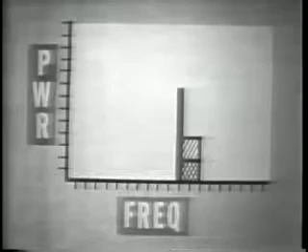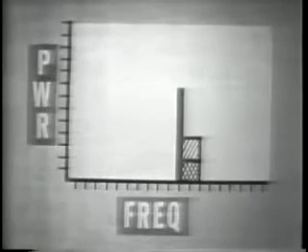And we'd still have the same intelligence in the remaining sideband. And by putting the power from the removed sideband into the remaining sideband, total sideband power is restored and is contained in just one of the sidebands.